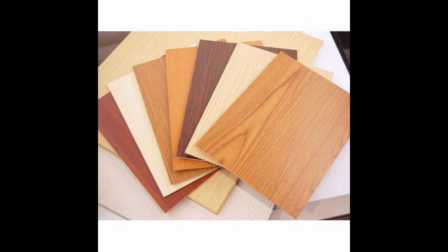There is usually an odd number of plies so that the sheet is balanced. This reduces warping. Because plywood is bonded with grains running against one another and with an odd number of composite parts, it has high stiffness perpendicular to the grain direction of the surface ply.